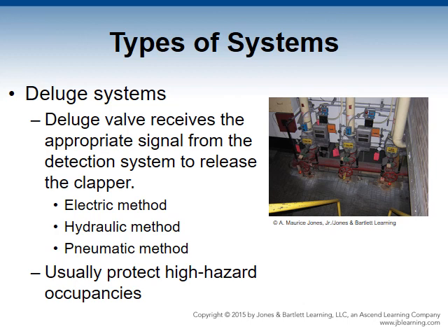Next, we have a deluge system, which operates in a manner similar to your pre-action system. Both require a fire detector activation or a manual station release to open the system valve so water will flow into the piping. However, the major difference is that these systems have open sprinkler heads without heat sensing release before water is discharged. Once water reaches the open heads, the discharge is immediate and simultaneous from all the sprinkler heads in the system. This arrangement provides large amounts of water over predetermined areas.